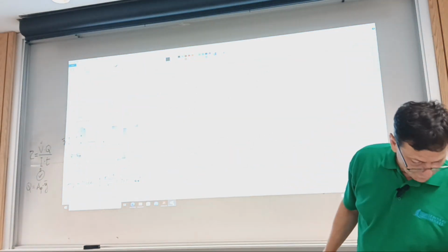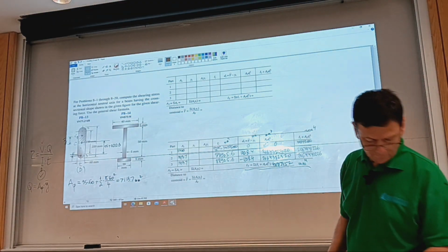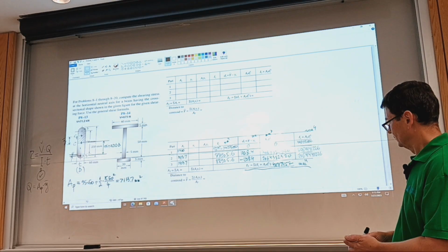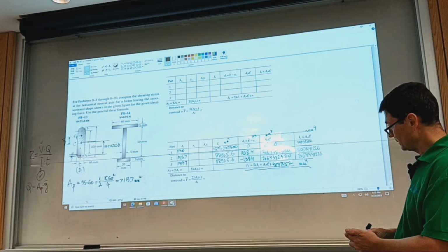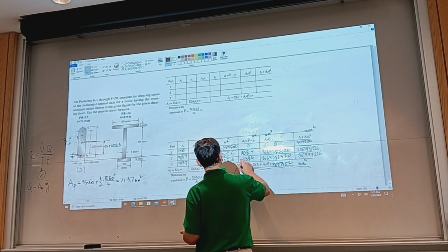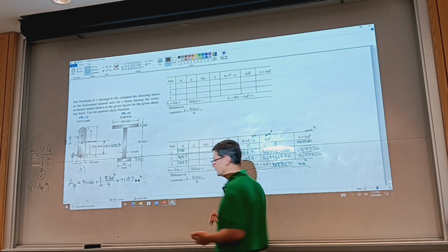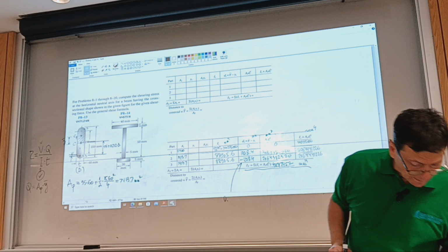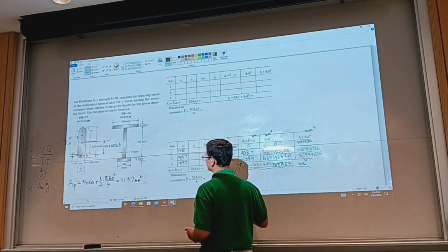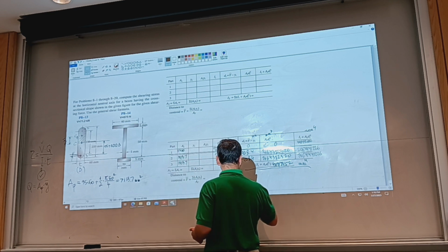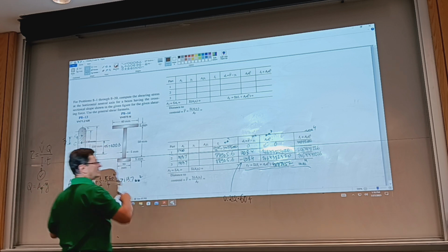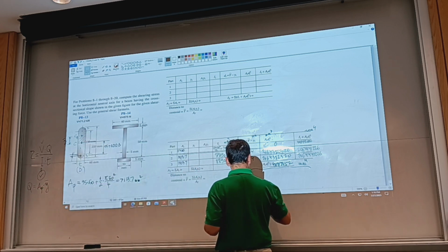How could it be 1208 if the whole object's only 200? I did some multiplication, I did something wrong. So let's take care of this. It's 0.212 from the appendix times the diameter, which is 60. And then plus this piece, half of 190, that's 95. But yeah, you're right, it's a good check, 1208 cannot make sense.